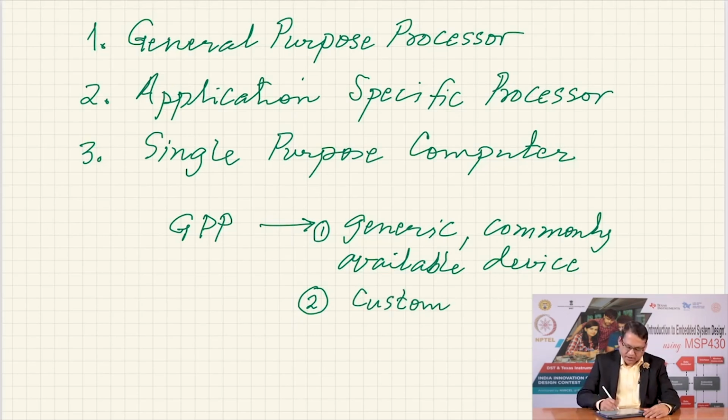And the third is this: existing companies could license you the code, the hardware description code for their processor, and you could acquire those codes in whatever way and target that code into a programmable logic device such as a FPGA. These are the three methods.